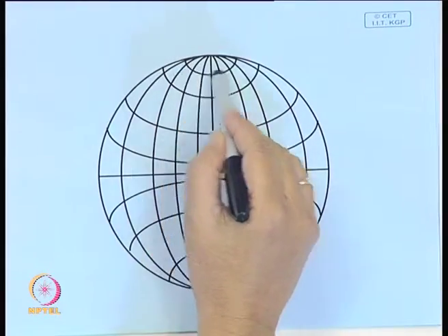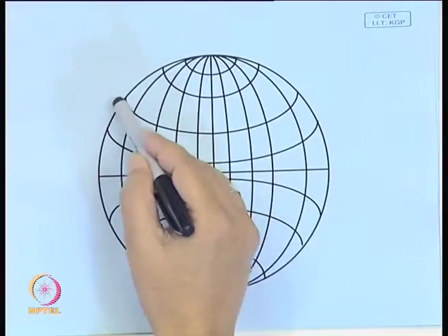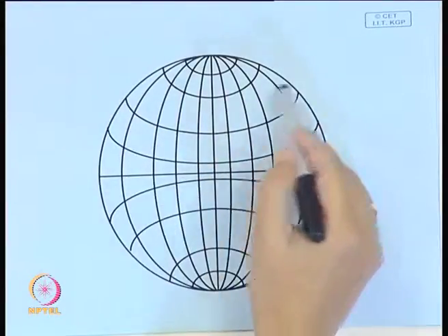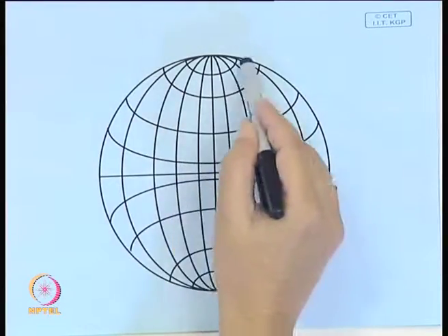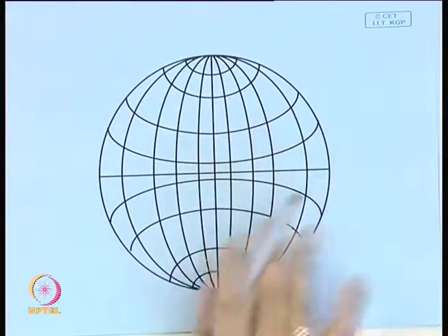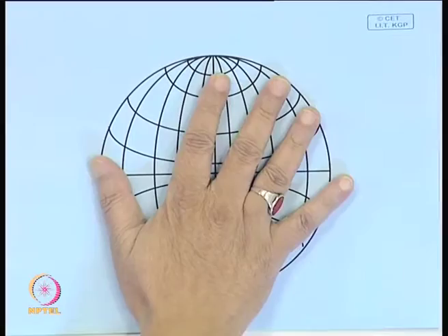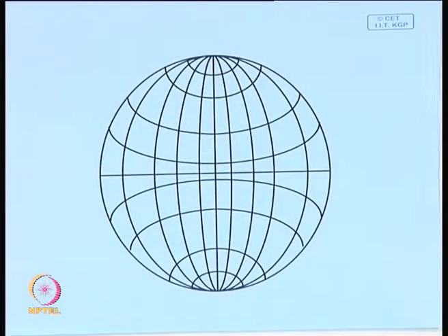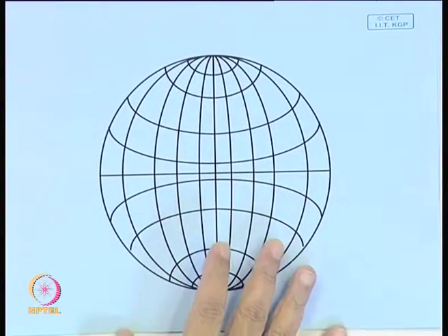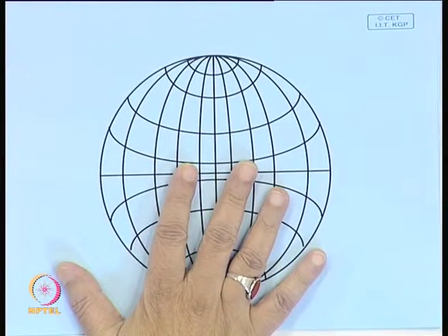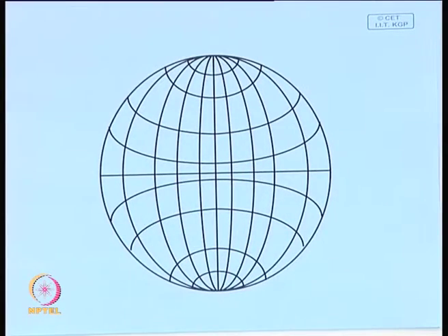You will have this kind of projections of these small circles like this, they are called latitudes. It is exactly similar to that globe, and this type of reference net that one uses is called the Wulff net, and it is used to perform angular measurements on stereographic projections.